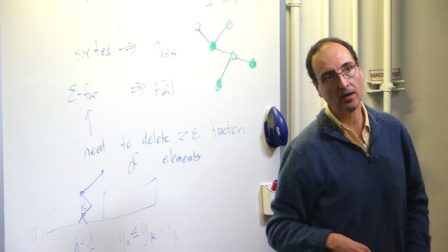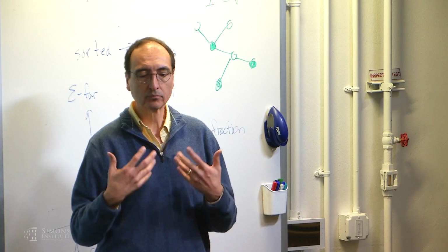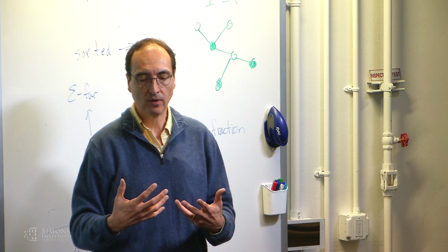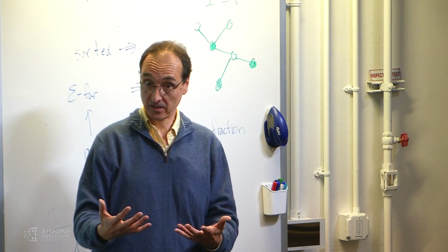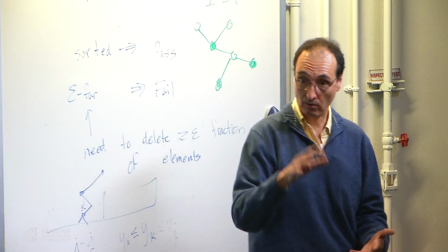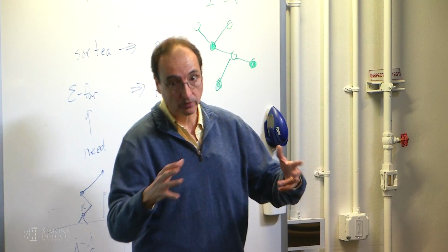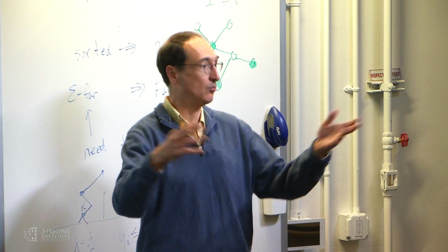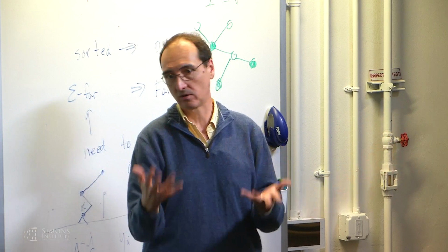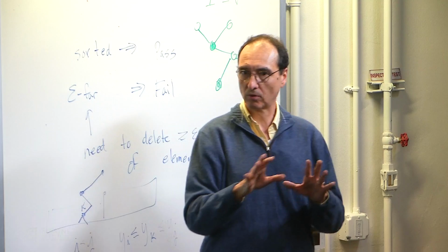And that's, I think, where you see control systems being applied quite successfully: in systems where you have good underlying physics-based models, for example. We're pretty sure what the laws of physics are for an airplane, or a room, or whatever. There may be variables there, like how many people are in the room, but I can bound that, right? I can say there's no more than however many seats there are, and there's a certain number of BTUs per person, and so that's an upper bound on the amount of heat load. So those are the situations where it works well.